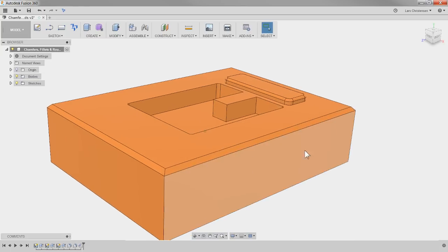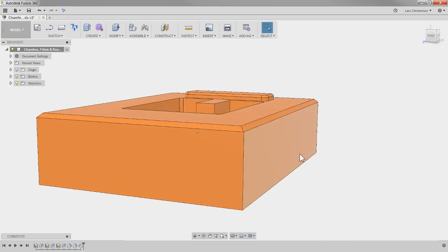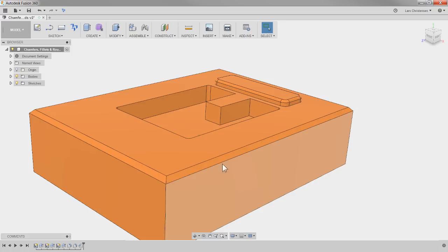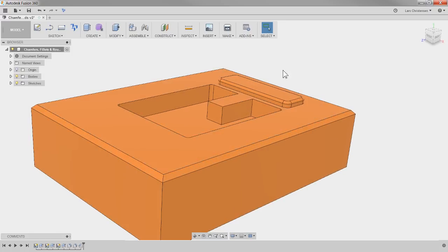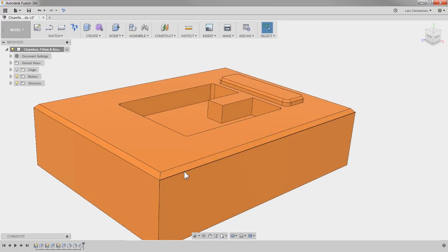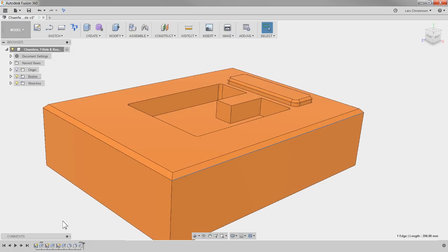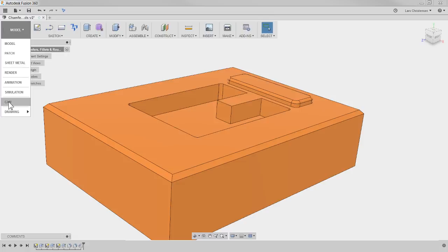3 millimeter chamfer, good chamfer here. Whenever you are driving a chamfer, we always drive the bottom one. So that's the first thing to add in there. Drive the bottom. So let's go back into CAM.